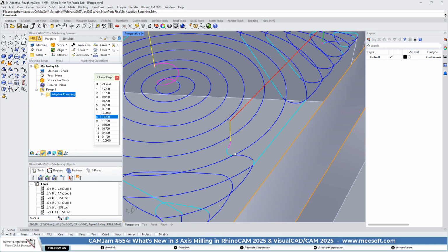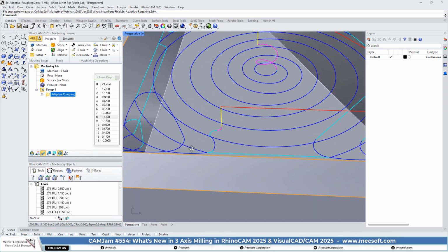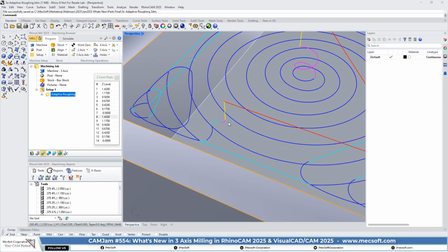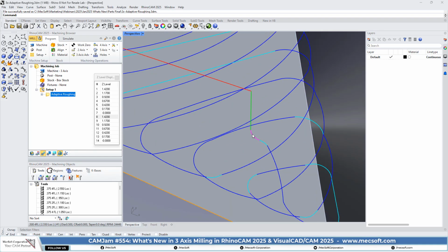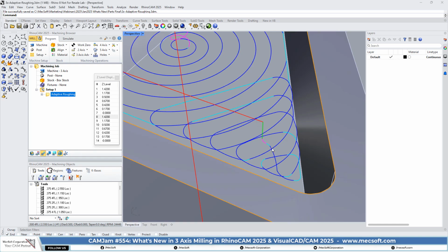So you'll notice here that in the retract, we have an arc motion and an arc motion and a retract motion, okay? So these arc motions facilitate the high-speed cut pattern itself at higher feed rates, okay? And then we also have arcs on the re-entry over here.